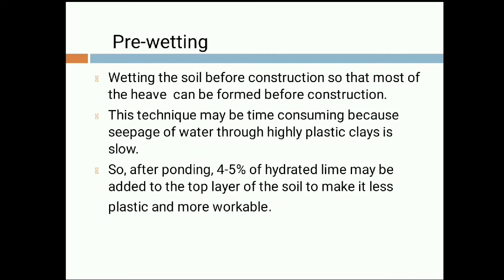Second one is pre-wetting. Wetting this soil before construction so that most of the heave can be formed before construction. This is very good. Before construction, if we wet the soil where we are going to construct the structure, it will try to swell, and if it has swelled before construction, there will not be much swelling in the soil when we start the construction process.